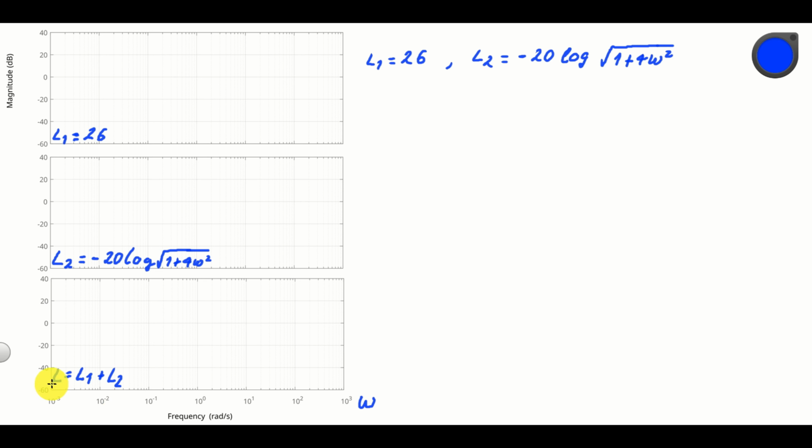On the other hand, on the vertical axis, we have 20 log of M, or we have our log magnitude. And you can see that we start from 0, then we have 20 dB, 40 dB, minus 20 dB, and minus 40 dB. How can you read decibels? Namely, if you remember the definition, L is 20 log with the base of 10 of M. When the magnitude is equal to 10, that is when the amplification of our transfer function is 10, then you will see 20 dB.